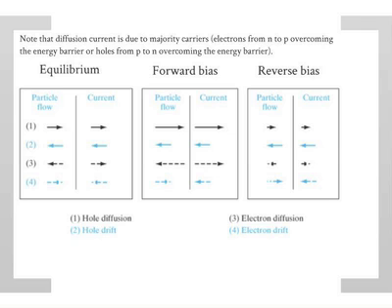And that's the electron current. That's the electron diffusion current. The cause of the diffusion current is majority carriers on one side injecting into the other side, where they become minority carriers, and then they diffuse. That's the physical picture that you need to keep in mind. And then we'll do that. So let's look at it qualitatively.